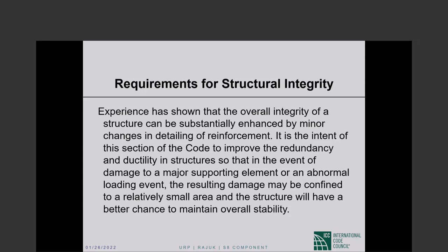And in the case of concrete, because we have a few lectures on seismic design, you will get quite a bit more information that will be more specific to the construction in Dhaka, particularly in the newer parts of Dhaka to the north, where the soils are poor, so that we typically have design category D. So this is one thing I wanted to say.